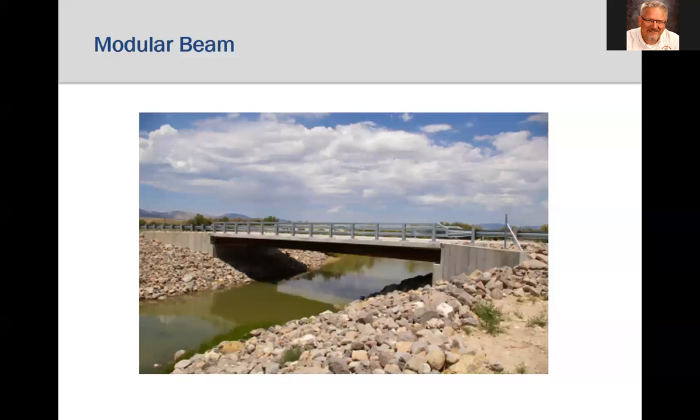According to the project engineer, we specified prefabricated steel on this project for several reasons. One reason was that steel beams are typically shallower than prefabricated pre-stressed concrete systems, which allowed us to keep a low bridge profile height. The second factor was cost. The prefabricated steel beams were less expensive than comparable prefabricated concrete systems. This was a larger traditional type rolled beam bridge that was modularized in the design, planning, and erection techniques to meet an accelerated bridge construction need.